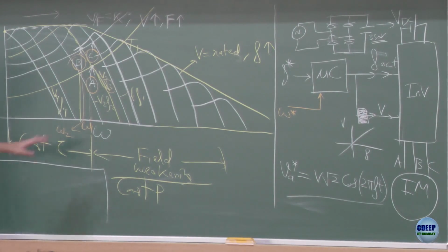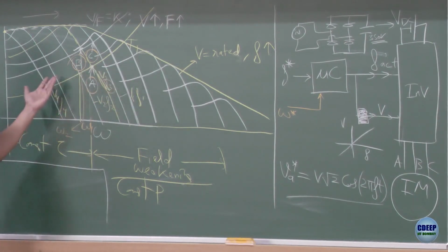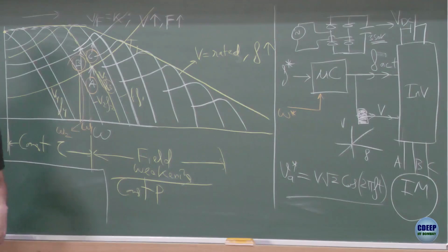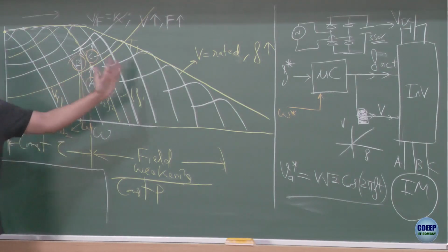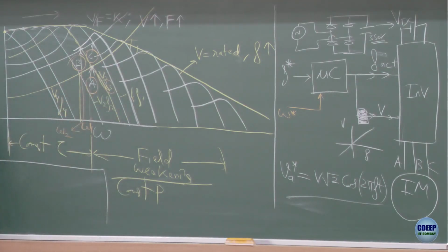Yeah, it depends on whether you are in the field weakening region or in the constant torque region. In constant torque, it would increase both. After that, it would maintain voltage and increase the frequency. Is that okay?